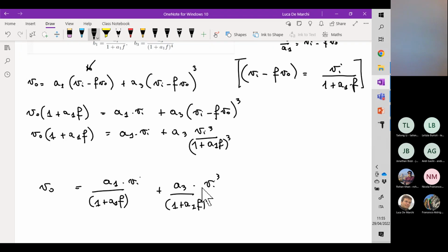So basically we get a reduction of the gain of the pure amplifier in terms of the DC gain by a factor which is 1 plus A null times F, but the same quantity multiplies the pole. So the idea is that in the logarithmic plot, we have a reduction of the gain, but this reduction is compensated by an enlargement of the bandwidth.